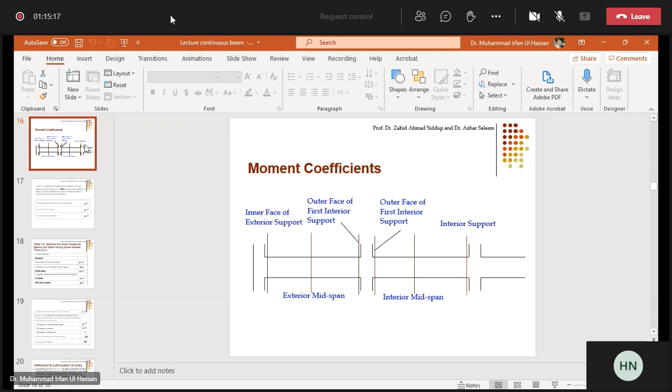And tension is at the top at the support. So if you are designing it as a T-type of beam, where the shape is like a T beam, then you see that in mid span the beam section has tension at the bottom side, and at the support the tension is at the top side.